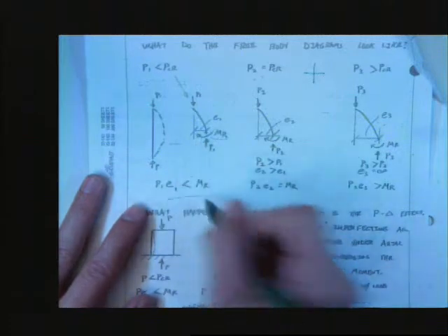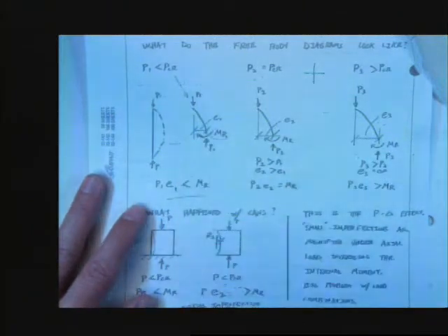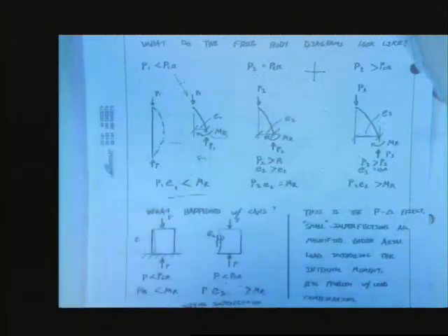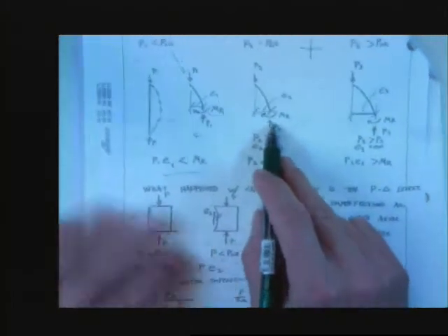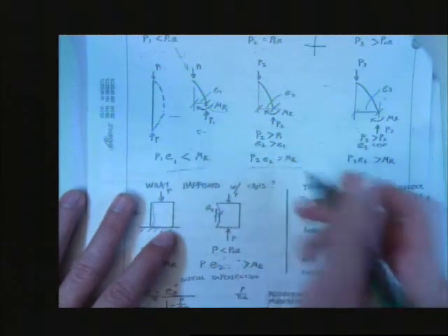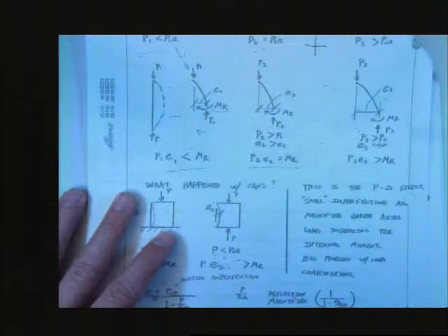You're good. You're safe. When you unload it, it'll just go back to where it was. It'll just move backwards. Okay? And when you get to this point where this internal restraining moment happens to be equal to this external moment, and that is right at the buckling load.